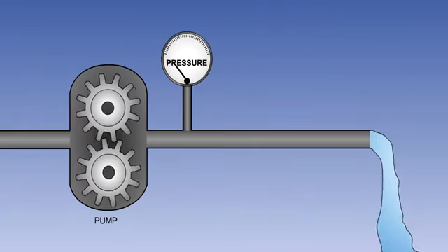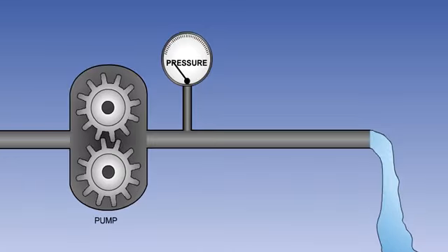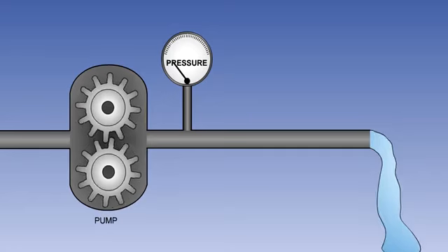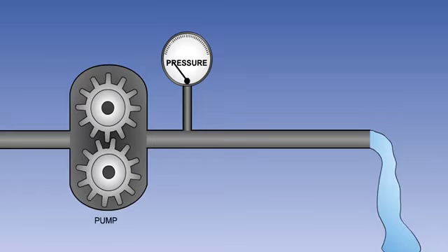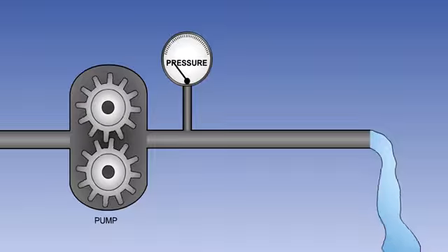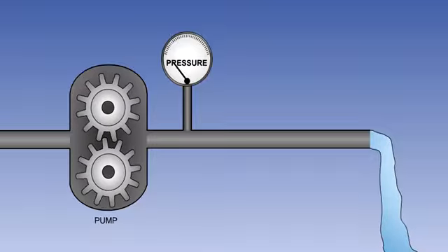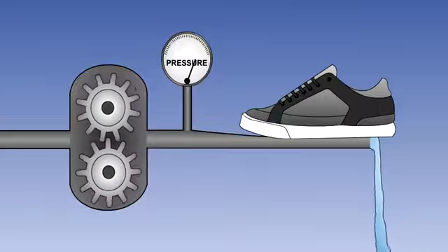For more complicated aircraft systems, a pump is required to deliver a flow of liquid into the system. It is worth noting that a pump in itself does not supply pressure. If it is pumping through an open-ended tube, then the fluid will have no pressure. In order for pressure to build, the flow has to be restricted.